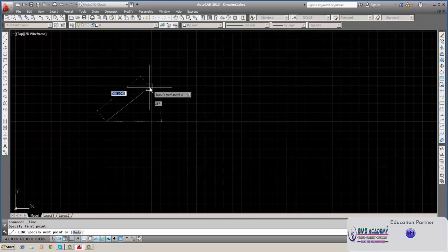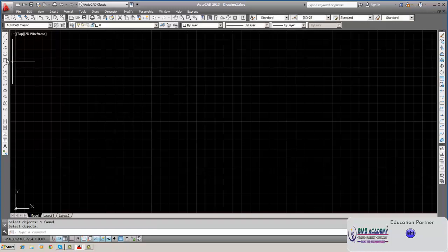Suppose I want to draw something somewhere here, 208.6 at 30, 45, you have to enter the values here and draw. So we have to enter the values if it is in snap mode. This is called snap mode because the movement will be only in multiples like this. And by clicking, you cannot draw fractions. You can draw lines only at the junction of the grids.